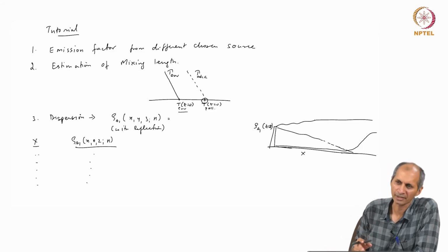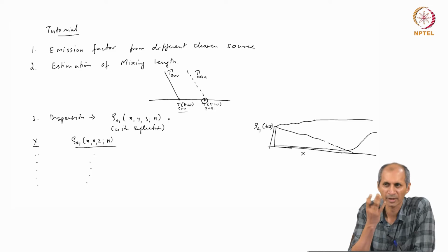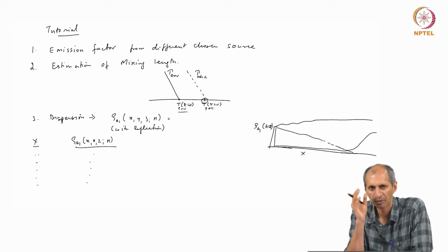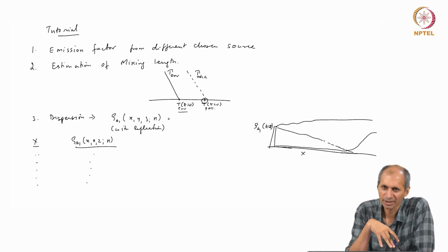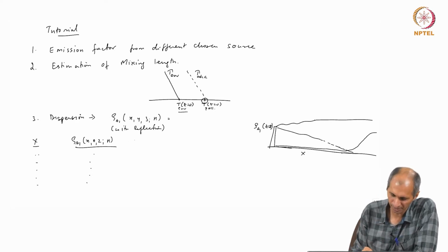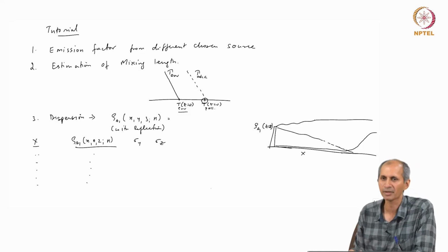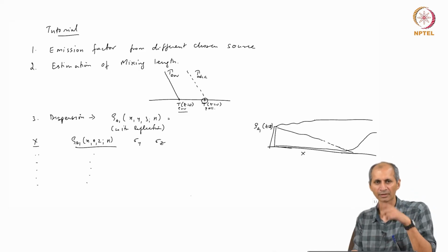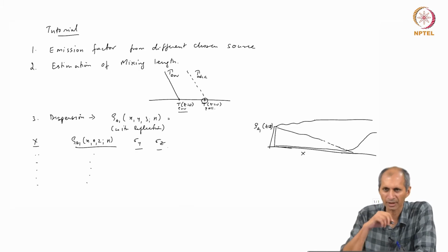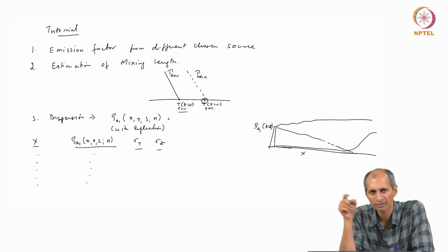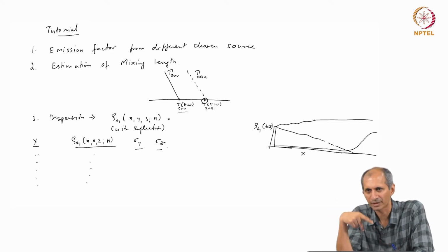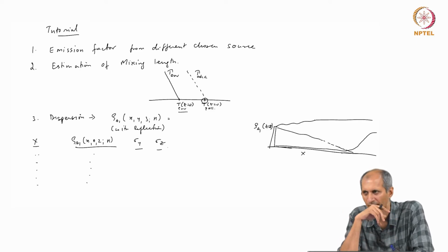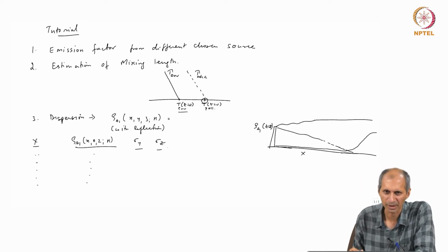This is a manual exercise. When you are doing AERMOD, this is done automatically by the software. The software will do 4000 points at one shot within 1 second. You can set it up to do in Excel also, provided you know the equations for sigma y and sigma z. There are mathematical equations. It is a little painful, but if you know the stability class, you can take the points from the graph, fit a curve and then use that curve. So automatically you do for one, you do for all of them. I think you can figure out how to do it automatically.